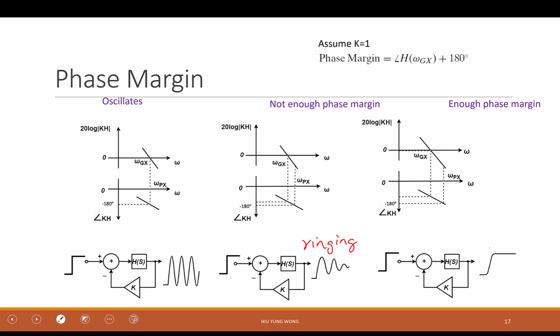You need a device that can sustain maybe 2x of what it's supposed to work at. So ringing is not good. Another problem is that when you're ringing, the signal is wrong. You cannot take it, so it takes longer to process the signal. Your whole system is actually slower. So you want to have enough distance between them so that when I have a step function, it will go up rather smoothly without ringing. And of course, this part is the time you need to wait, unfortunately, right?